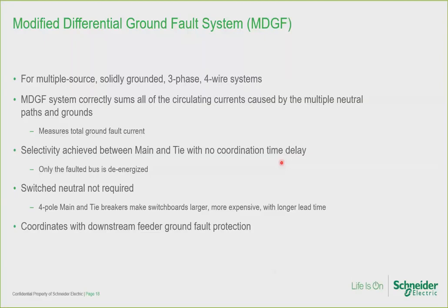In this presentation, I demonstrate MDGF on a dual source main tie main system because once you understand how it works on that system, you'll understand the concept of MDGF. But I note that MDGF can be configured for systems having more than 2 sources, including generators and transformers.